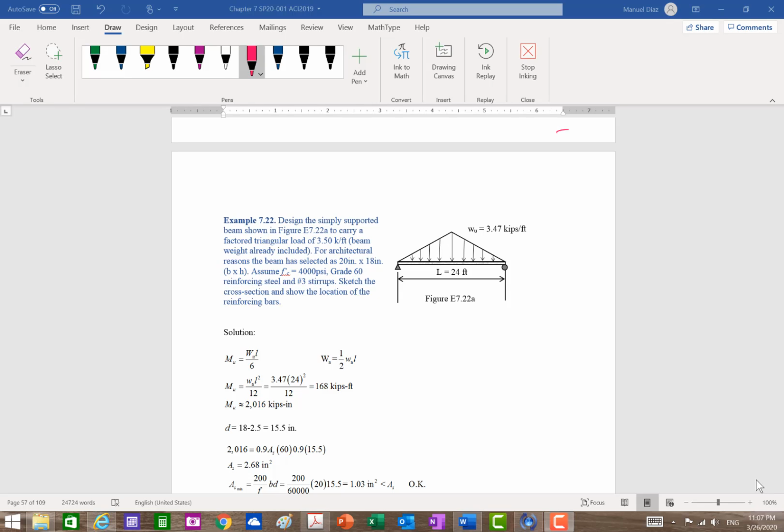All right, so this one is your part 4 video on chapter 7. So far you have learned how to design for the case of dimensions being given, or dimensions that you find. You can find the dimensions using your Table 9.3.1.1 in ACI 318.